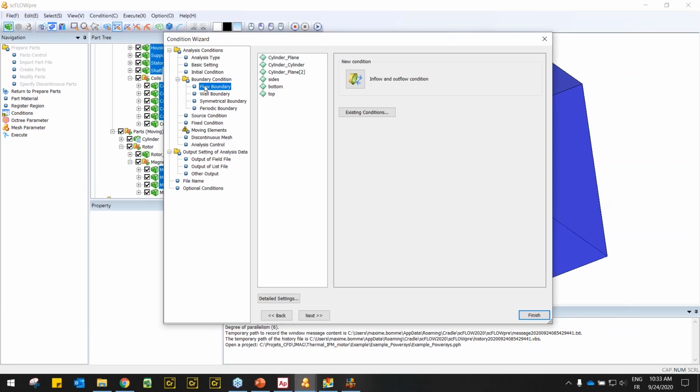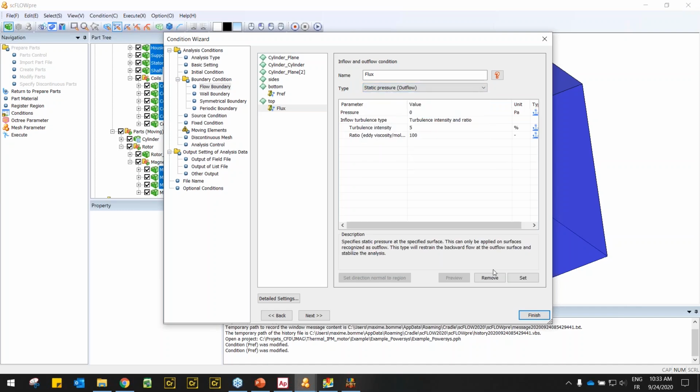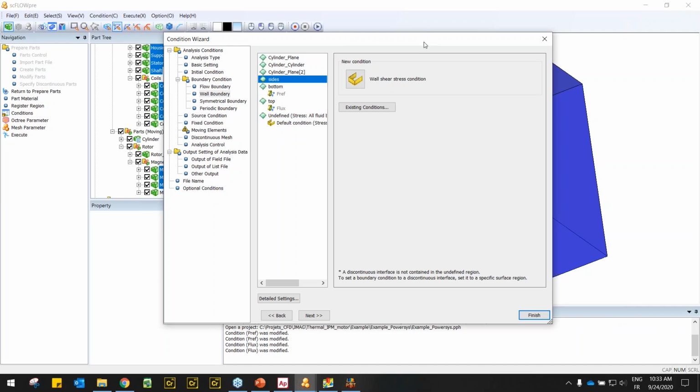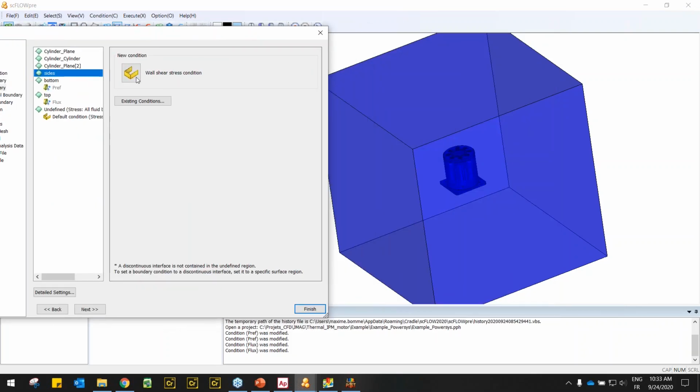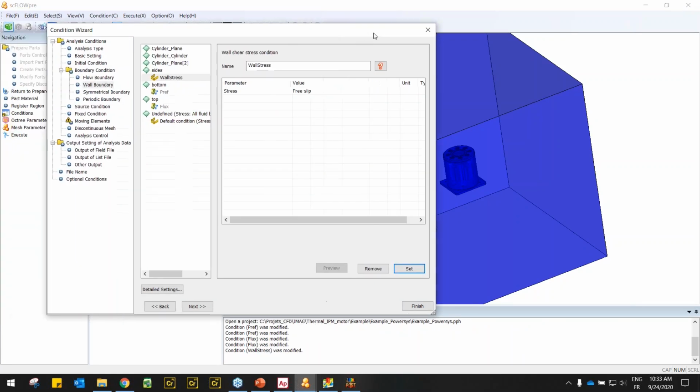Regarding the boundary conditions, that's why it's important to identify regions, because here I can say, for example, on the bottom side, I know that I will have a pressure reference, maybe the atmospheric pressure, okay? Let's remain on 0 Pascal, sorry. On the top side, maybe I can just say, okay, it's open to the air. That's it. We can also say, for example, that the sides of my plenum are virtual walls, so I don't want any pressure loss to be calculated along them. So I will just specify virtual walls.